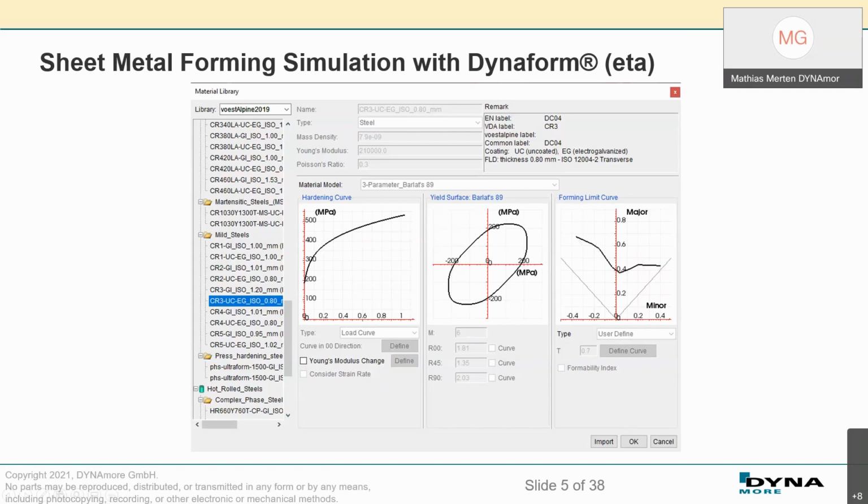And if you do not have this available, you can also use the well-known Keeler formula to estimate that, or the more modern approach by Abspoel and Scholting, which is here referred to as Tata Steel, but not shown on this picture. Why do we need this? We would like to calculate the Formability Index, and therefore we need this FLC.